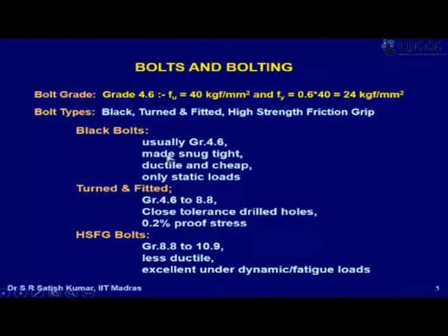So they are just put, and then we do what is called snug tight. That is, we go on rotating the nut with fingers. Let's say we may use a small spanner, but we are not trying to rotate the nut beyond what can normally be done with a very small torque. So that is called a snug tight position. And beyond that, if I want to rotate it, then I need something called a torque wrench or a spanner with a larger lever arm.